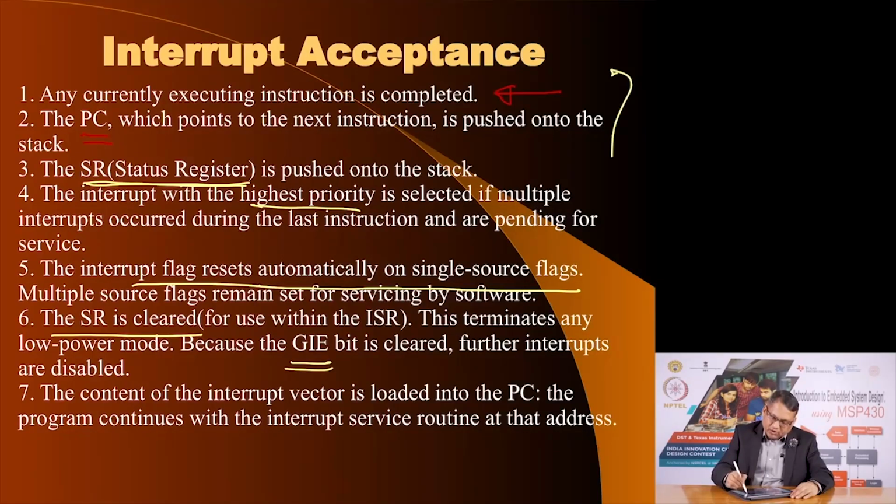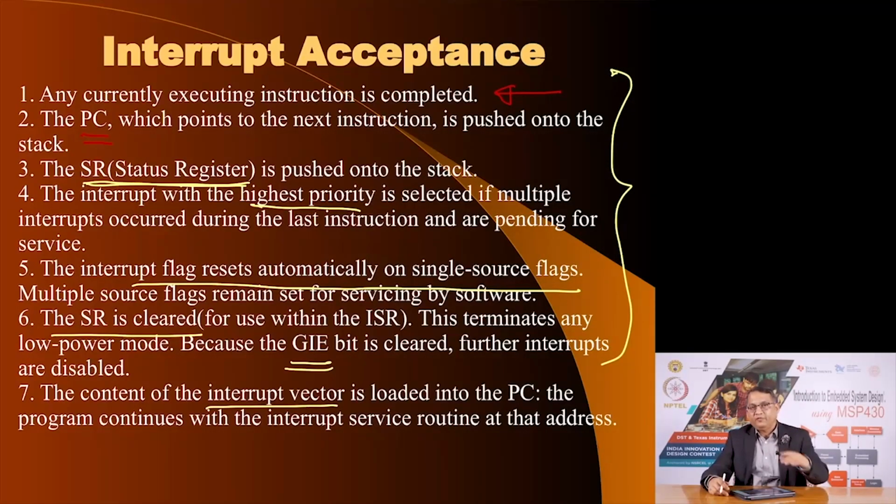Once these conditions are all met, then before you go into the subroutine, the interrupt vector is loaded on the program counter, and from there the microcontroller starts fetching and executing the instructions of that subroutine.